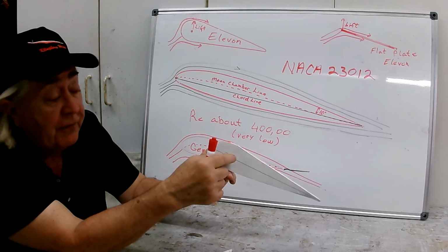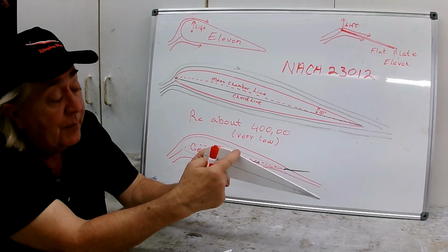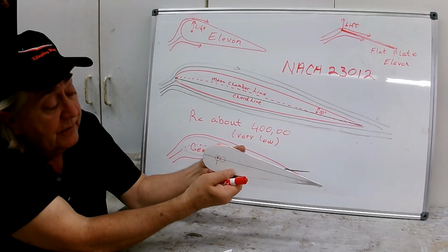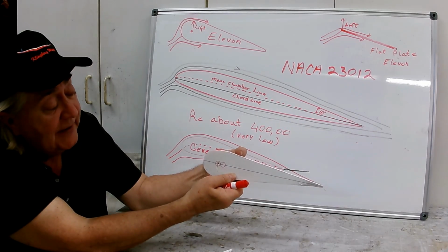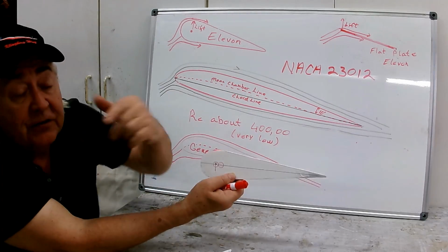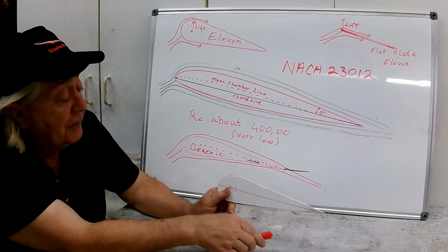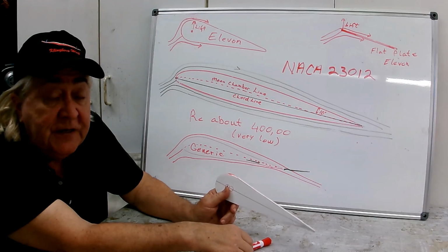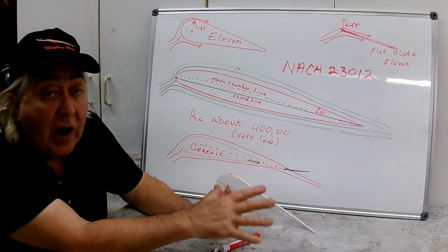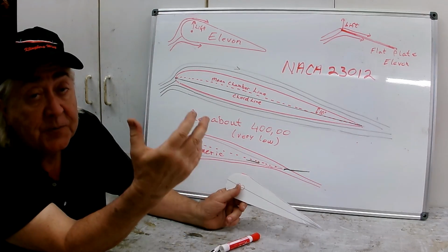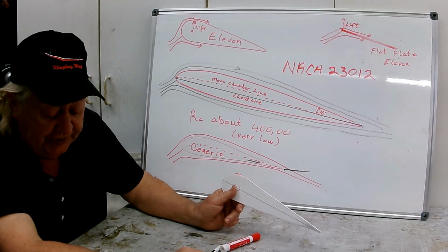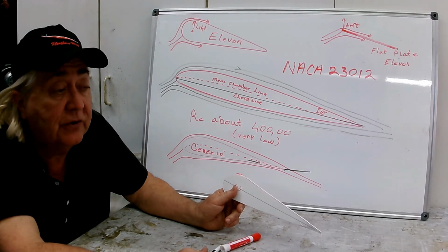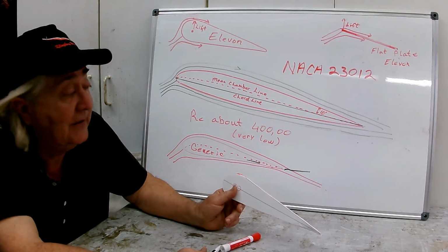Now, what we saw in the flight video is the flow begins to separate right about here, maybe an inch past the hinge line, and it just turns 90 degrees and goes out along the span. Horrible situation. And the video where I do the CFD analysis talks about why the flow is doing that, at least my speculation. There's not really any papers I could go look up. I don't think anybody's ever analyzed this problem before.